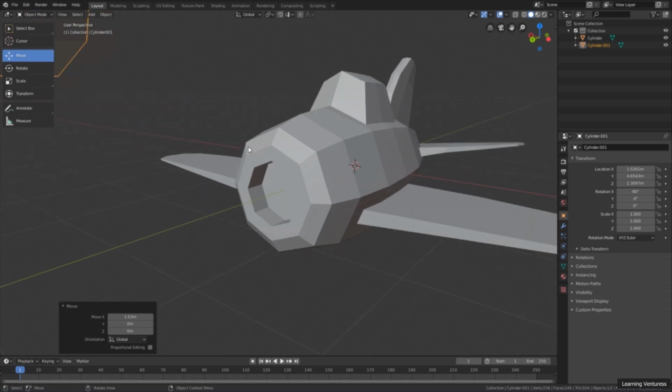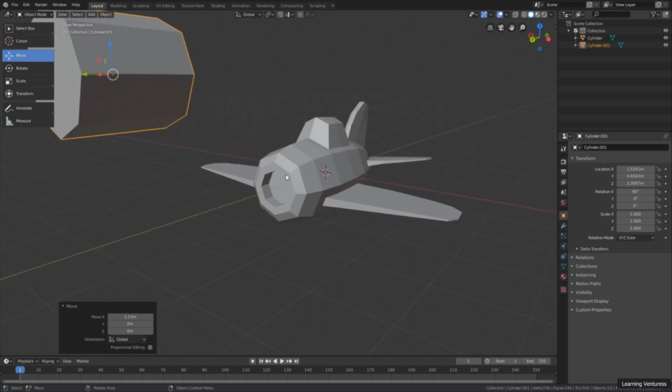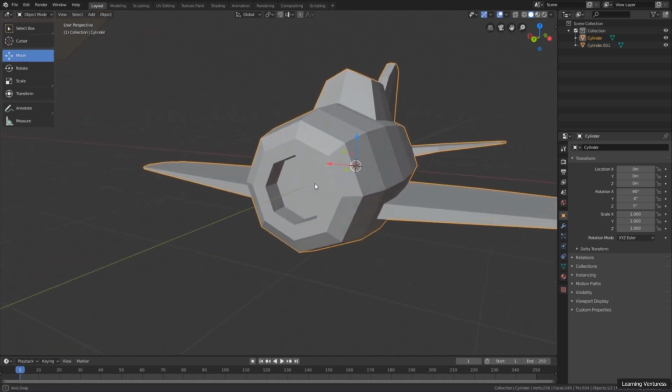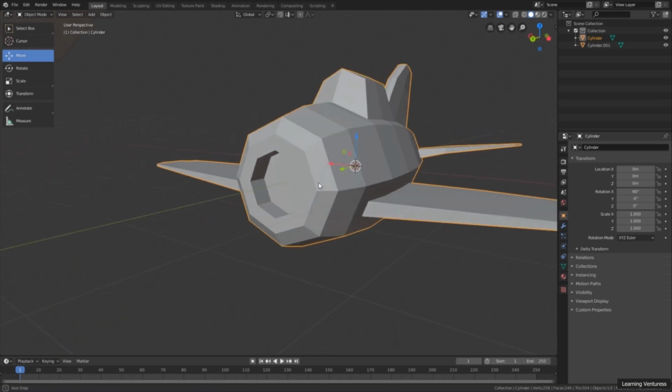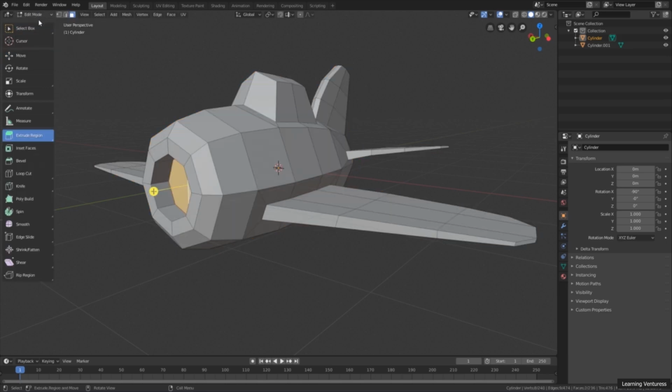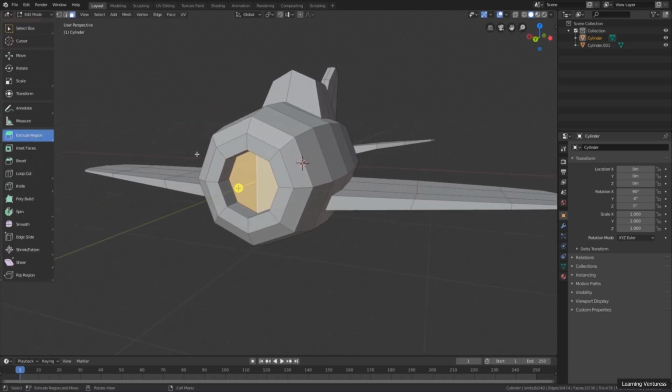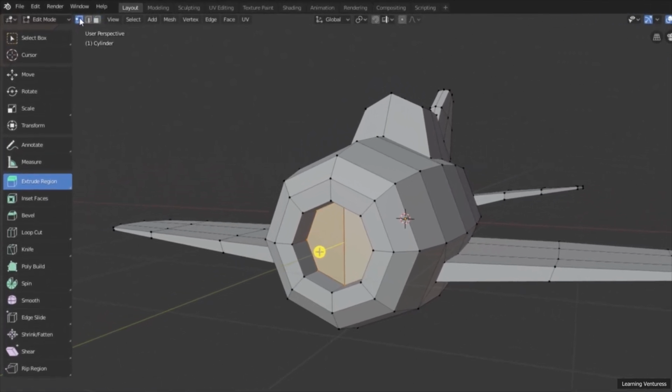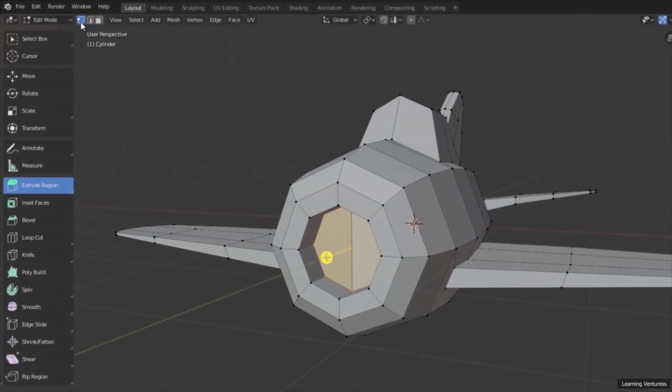Okay? And now, to start the alignment, we are going to select the target object, which is the airplane, and we are going to enter the edit mode by going up here to the interaction mode menu. Okay? And we are going to use the vertex selection mode. So up here in this region, we are going to click and activate the vertex selection mode.